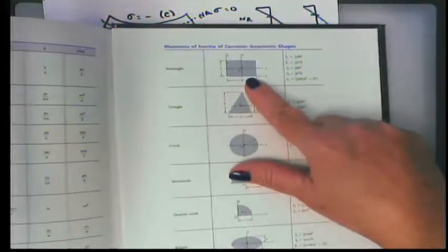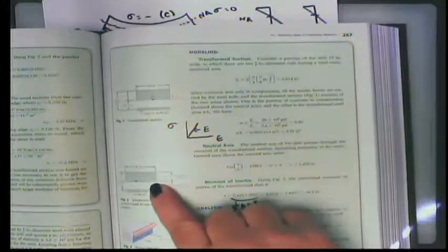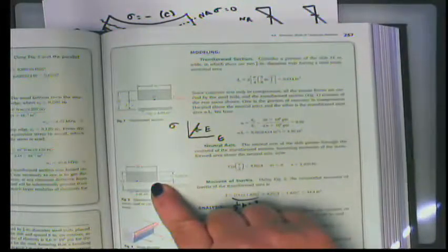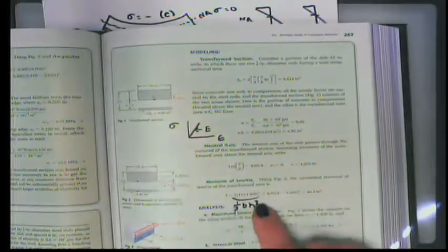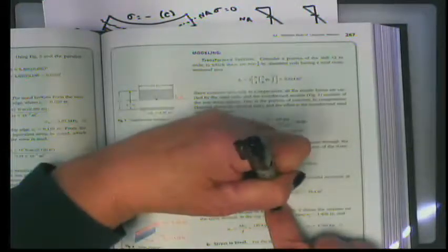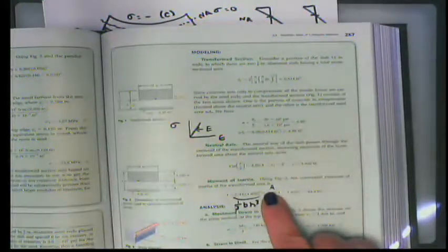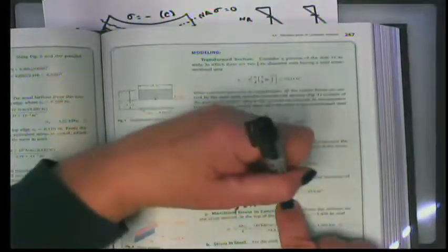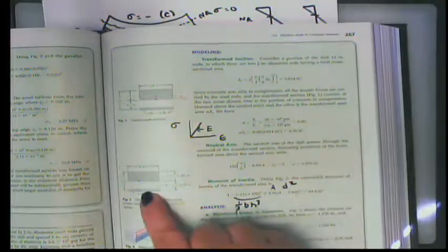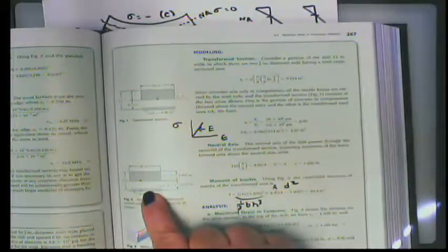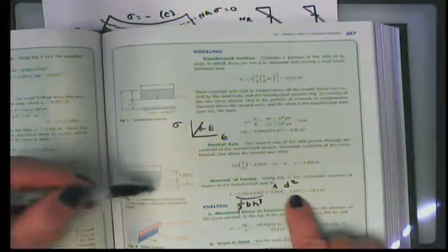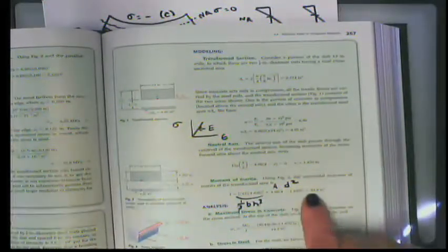Because the base of our section is the neutral axis, which is what we are taking the moment of inertia about. The next one, this is the area, the transformed area of the rebar times the distance squared between the location of this transformed area and the neutral axis. So that's the total, 4 inches minus x, 1.4, and we get a moment of inertia in inches to the fourth.